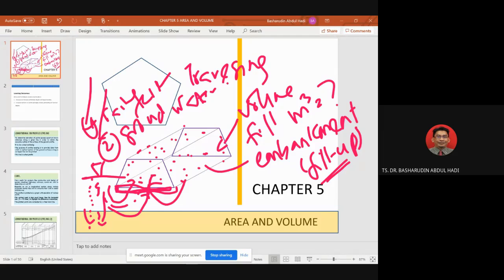So we must give good protection to the embankment, because we don't want the road to settle when we have water soaking the base of our embankment, or the road base or sub road base, meaning that the structure is going to break down. So that's why we always control the water. Alright. Okay. And actually, for area and volume, we just want to calculate them.